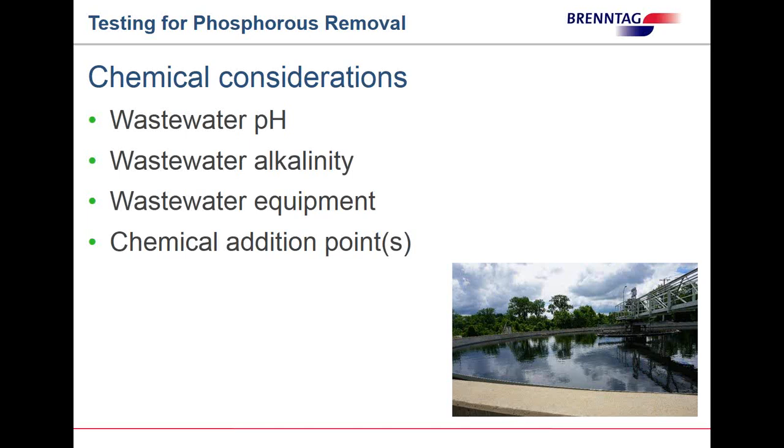Ferric and ferrous products may interfere with ultraviolet transmittance, UV, used for disinfection in some wastewater treatment plants. And then plants with primary and secondary clarification may treat at both stages, with the secondary acting as a polishing stage. This can also help with chemical feed efficiencies. Next.